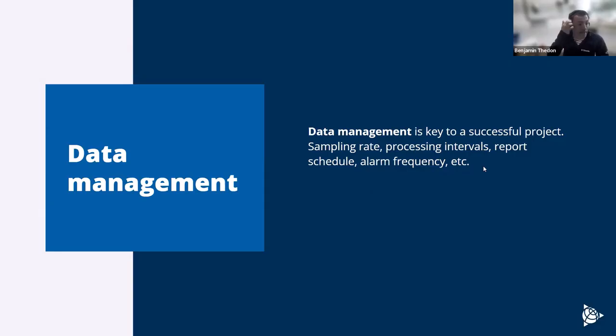And then the data management. Data management is also key for a successful project. Different parameters have to be defined, like the sampling rate or the processing interval on your processing software, on Trimble 4D for example, or the report schedule or the alarm frequency.